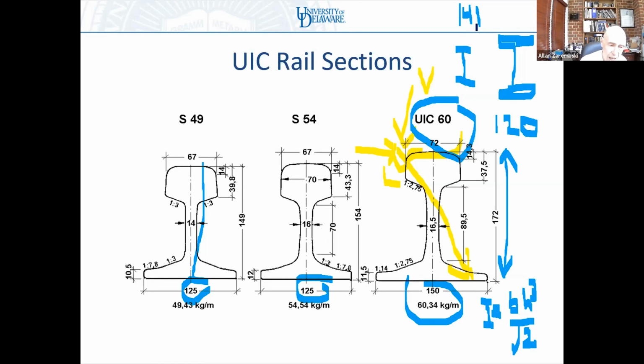And that's because of the higher loads. Now, I will say that for many, many years, the Russians actually had a heavier rail section. The Russians actually went up to about 75 kilograms per meter or higher. I think they've scaled back a little bit. And I think now they're equivalent to the AAR world with about 70 kilograms or 140 pounds per yard as being the highest sections they have.